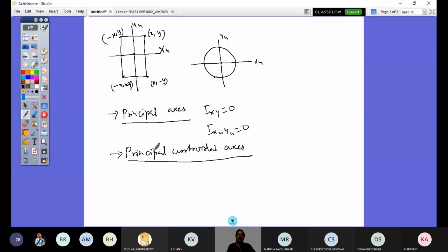So for that purpose, you require to locate section orientation, and the axes are going to be principal axis, and principal axes are the axes when the product of inertia is 0, right? So that you should understand. So for these two sections drawn, these axes are not only called centroidal axis, also called principal axis.